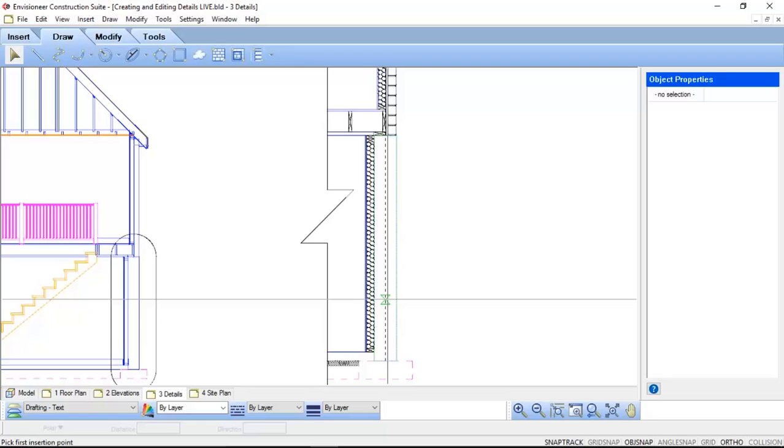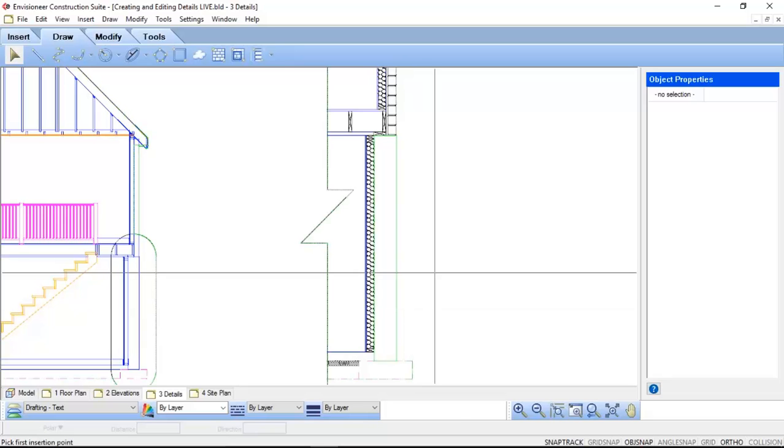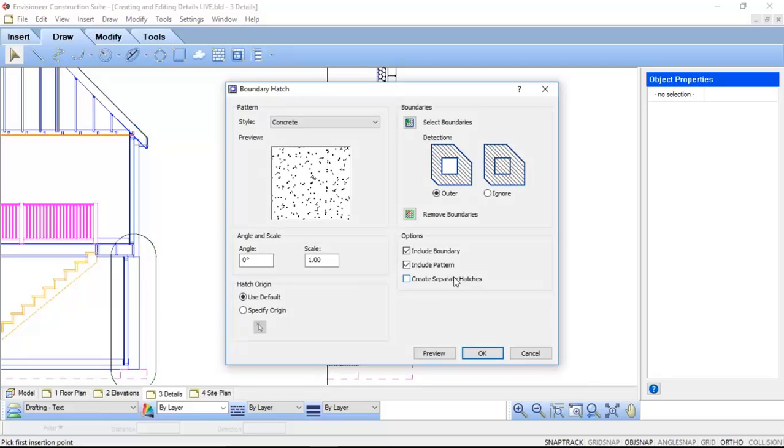In this case, I'm inside my stem wall, so I'm going to go ahead and click. You can see that it turned green. It's highlighted green now, that line around the perimeter. If there were more areas I wanted to choose, I could go ahead and select more areas. I'm done for now, so I'm going to right click and choose enter. That's going to bring me back to my dialog.